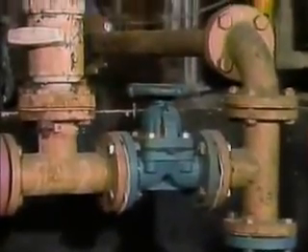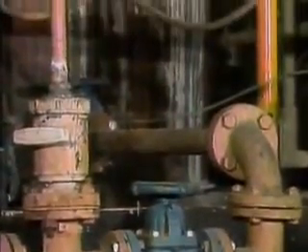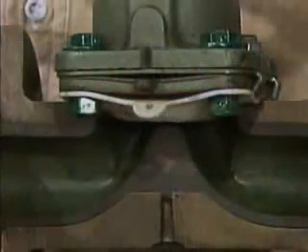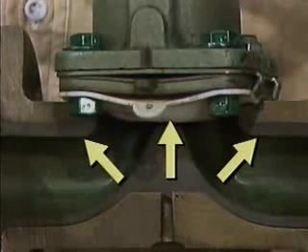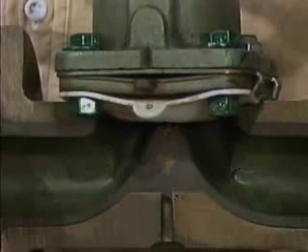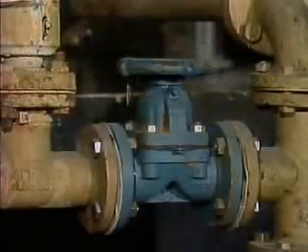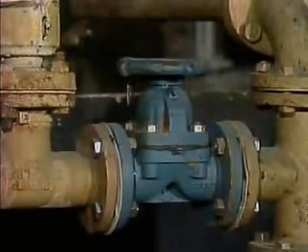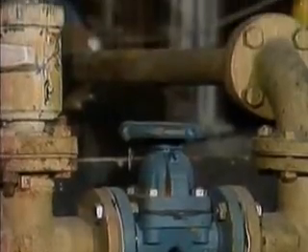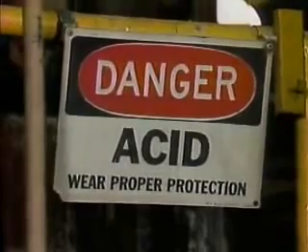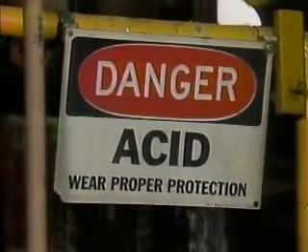For that reason, diaphragm valves are commonly used in applications that involve corrosive materials and abrasive slurries. In addition, some diaphragm valves have protective liners made of plastic or a similar material. The liners protect the diaphragm and the valve body from damaging fluids. In short, diaphragm valves are widely used throughout industrial facilities for a variety of applications, but they're particularly useful in systems that carry chemicals or hazardous gases.